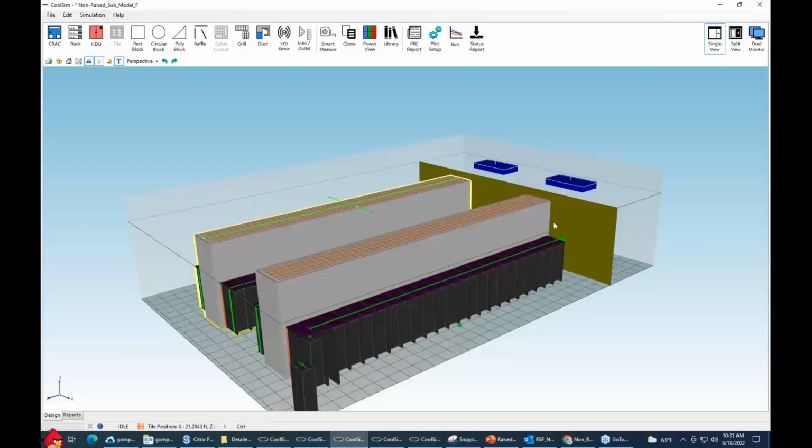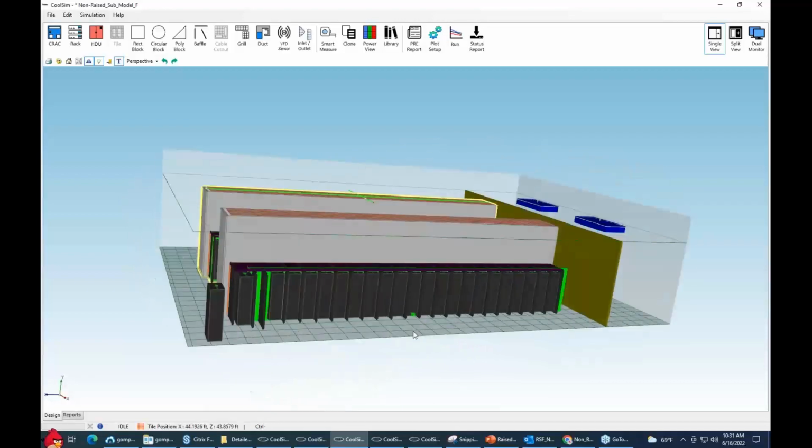So if this situation up here is leaking for some reason, then all the air is going to escape into the ceiling plenum. There'll be no cool air further downstream. And they always leak. The question becomes, how much do they leak?